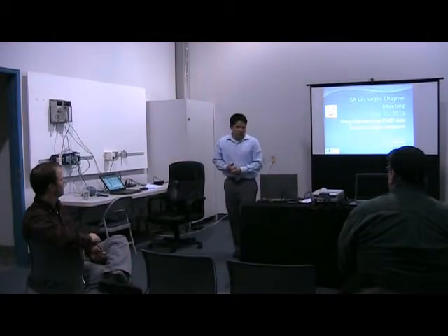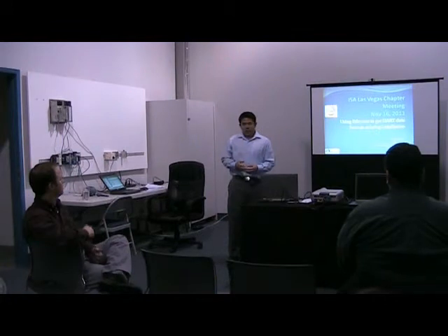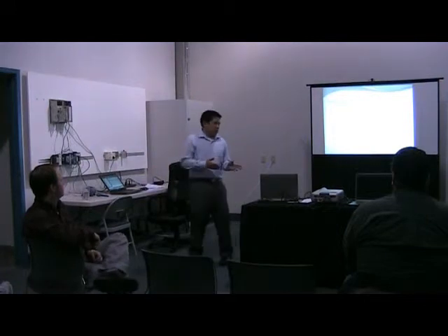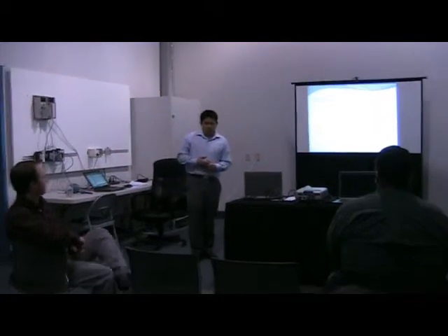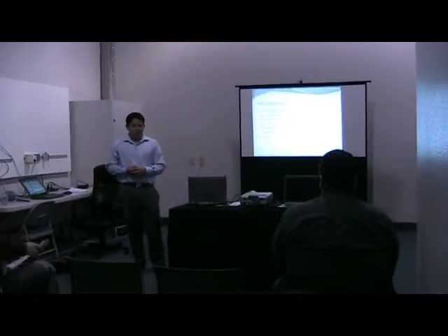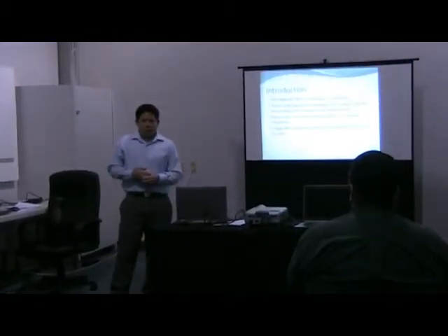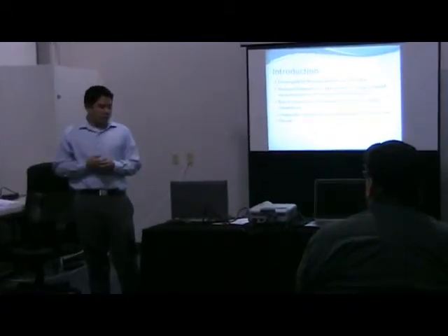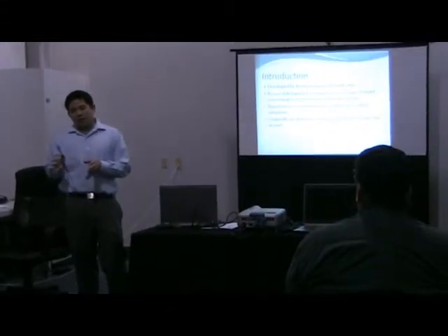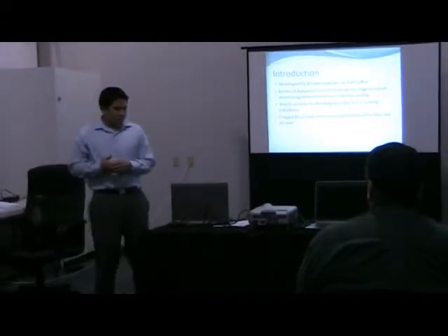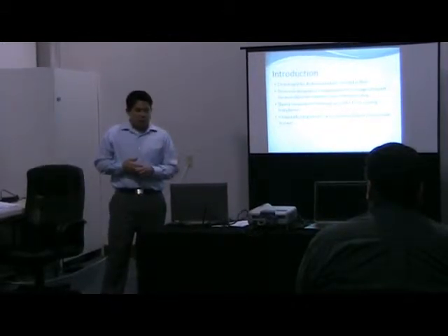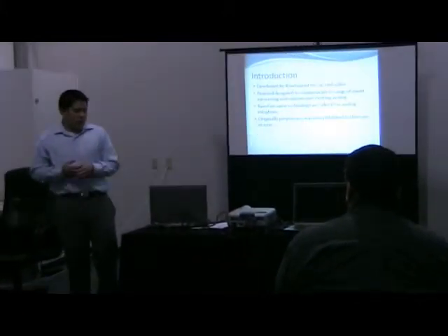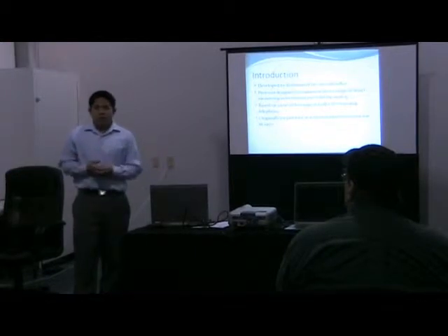Okay, so I'm here to present today on using Ethernet to get HART data over an existing installation. But just to start out, a little history on the HART protocol. It's been around since the mid-1980s. It was developed by Rosemount Incorporated. It was designed as a protocol to communicate with a range of smart instruments and devices over the standard 4 to 20 milliamp signal. It's based on the same technology that brought us caller ID over analog telephones. It was originally proprietary and was later published for free use in the 90s.